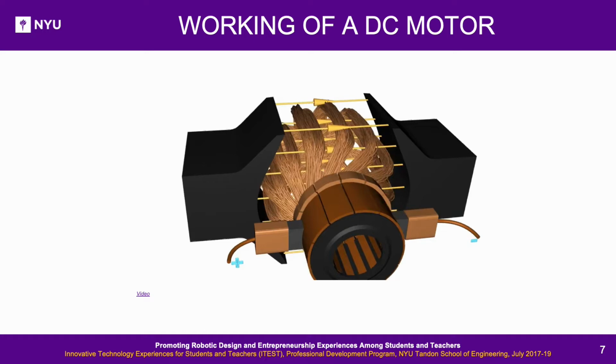If you observe the torque action closely, you will notice that when the coil is perpendicular, the torque is less, which creates an irregular motion of the rotor. To overcome this, one more loop can be added, with separate commutator arrangement, so that when the first loop is vertical, the second loop is connected to power source and there is a constant and stable motion. As more such loops are added, the rotation will get smoother.